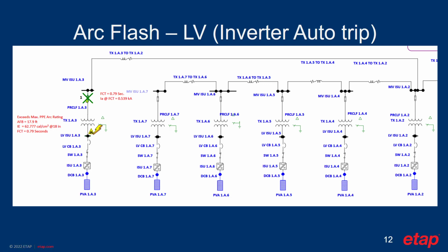And at the same time, the inverter would shut off by itself because of its terminal voltage being less than 50% of the actual nominal voltage of the connecting switchgear.